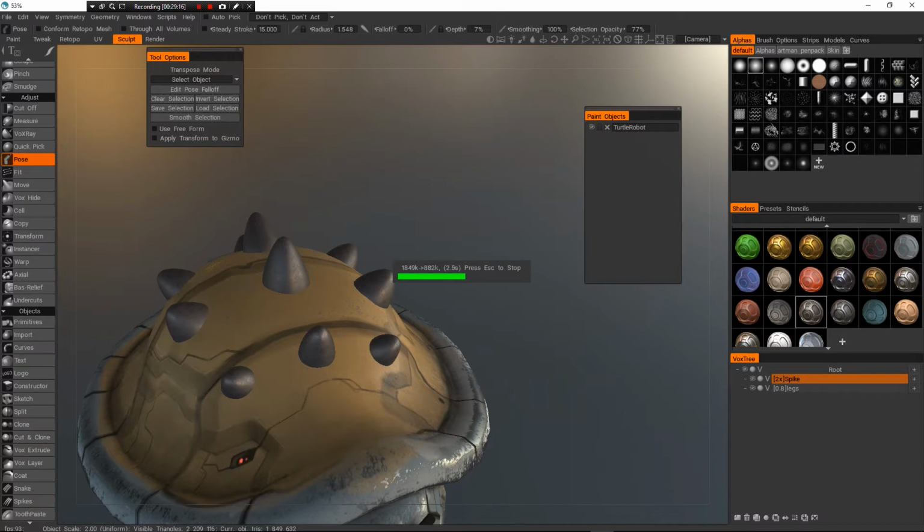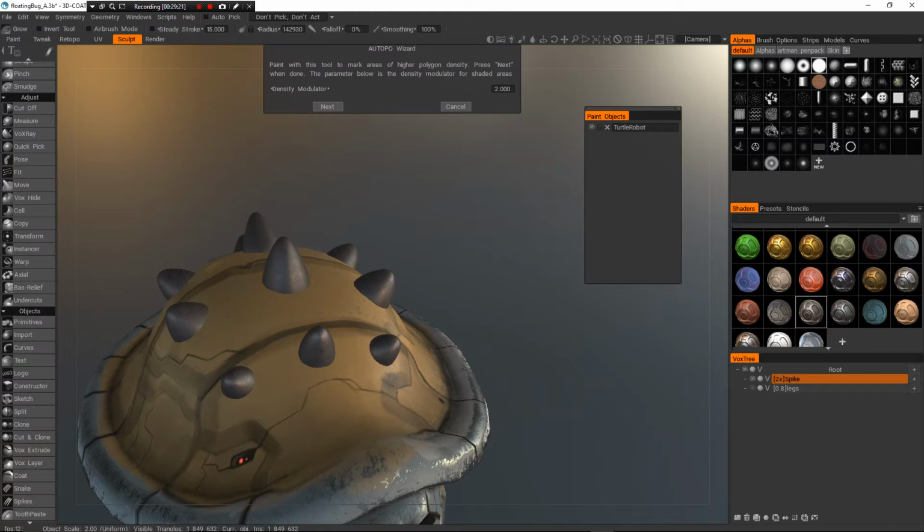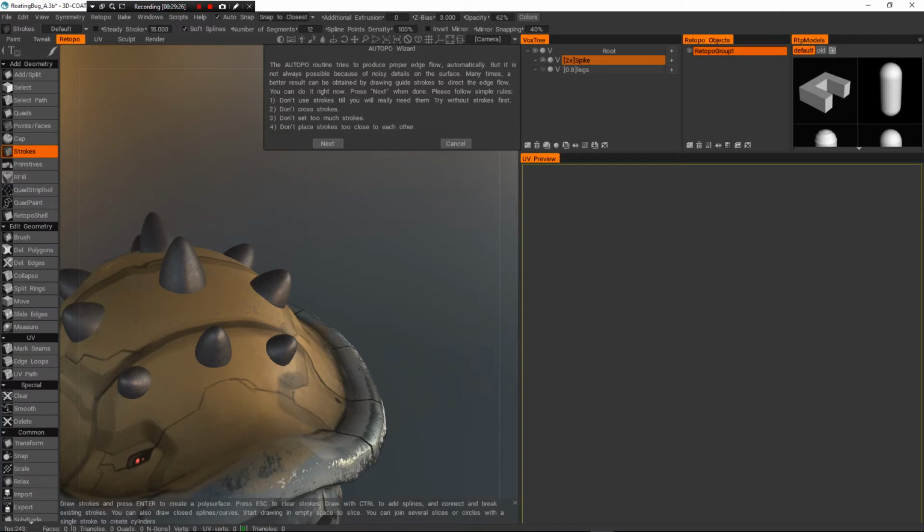This is a process you can also do manually. But because these are not really going to ever be deforming or anything like that, I don't mind doing it this way, because it generally produces fairly good results. If you've used ZBrush, this is very similar to ZRemesher. The main difference is this is not used to continue sculpting, it's used to move to the next step in the pipeline, which is generally going to be unwrapping and texturing.